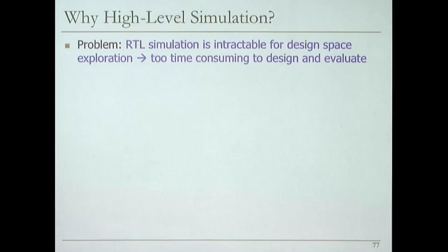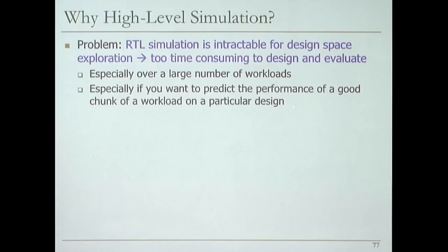For example, even for the reinforcement learning memory controller, it takes a lot of time to do the RTL simulation for a real workload for a long enough time, right? Especially over a large number of workloads. If you want to actually study a huge number of workloads, it really becomes intractable. In RTL simulation, perhaps you can wait for a day and you could execute 1,000 instructions, right? Something like that. But the real workloads take, I don't know, trillions of instructions, or even more.